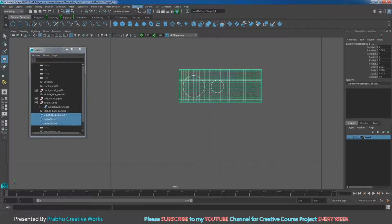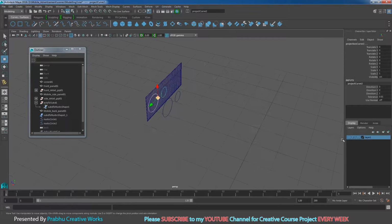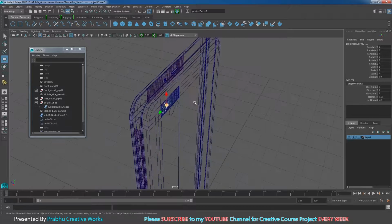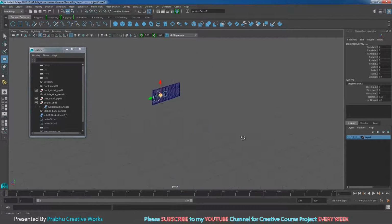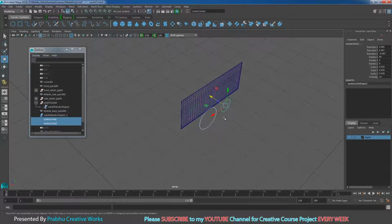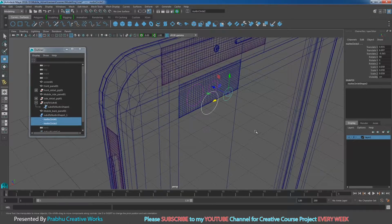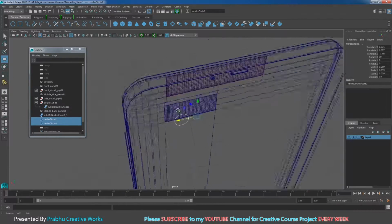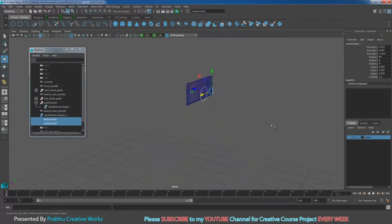Go to surfaces and choose project curves on surface. Now go to perspective and check whether it is correct or not. It will be perfect, so I will hide this layer. Now I will select both objects and move them a little bit over here, so that your projection will follow. I will unhide this one again and check it is perfect. Okay, so I will hide this one.